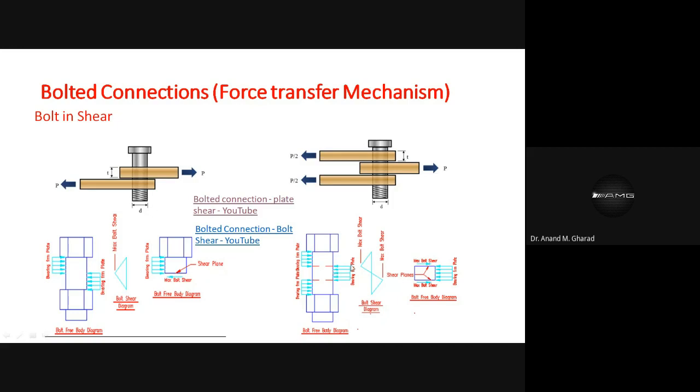These are the bearing stresses from the plate. And if we draw the shear force diagram associated to this, what do you observe? There are two peaks, two shear failure planes, as we call them in short. So when there are three plates, there are two shear failure planes as shown over here. Similarly, if we have two plates, how many shear failure planes do we have?